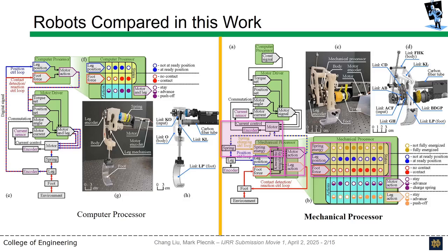These large torques lead to spring deflection, forming an elastic energy reservoir that can be slowly charged while out of contact with the ground, and rapidly released immediately after contact is detected to push off the ground, forming a new functionality executed by the spring charging control loop, labeled in this diagram. This third subtask is not possible by the robot on the left.